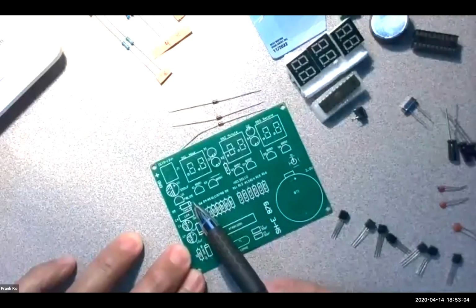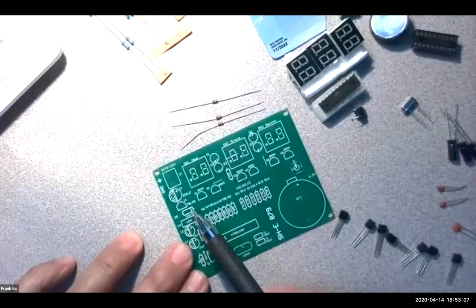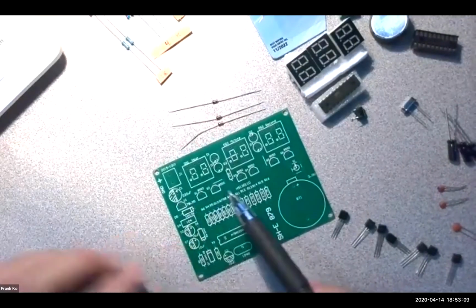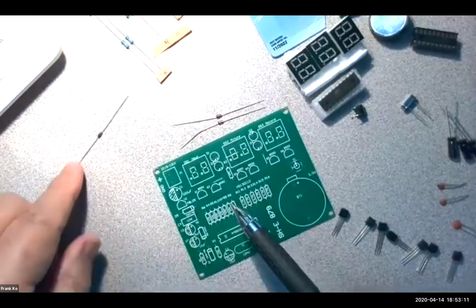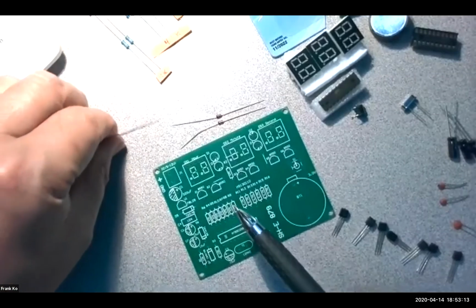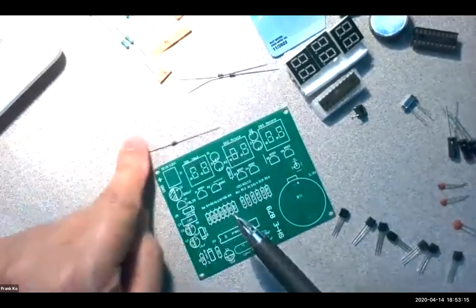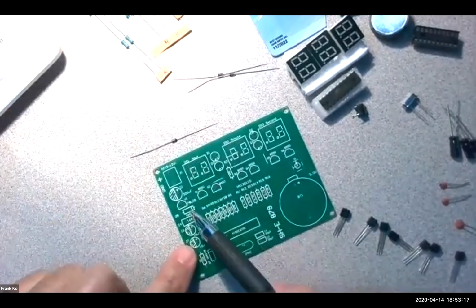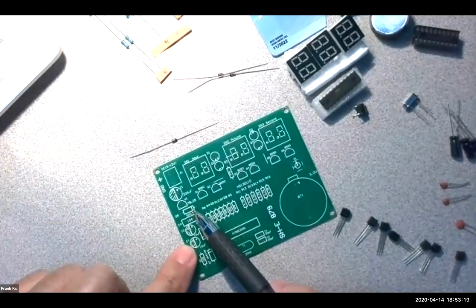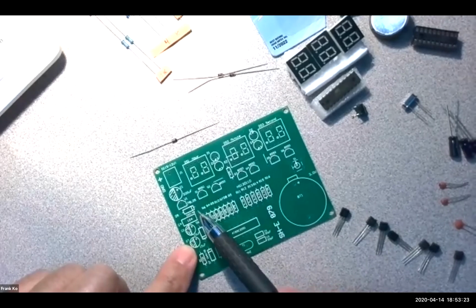The cathode is the black banded N, the negative side of the diode. It happens to be on the right-hand side. So if I'm going to use this diode, I have to turn this guy around, like so. So the black band is lined up with this band on the 4148 symbol on my board.